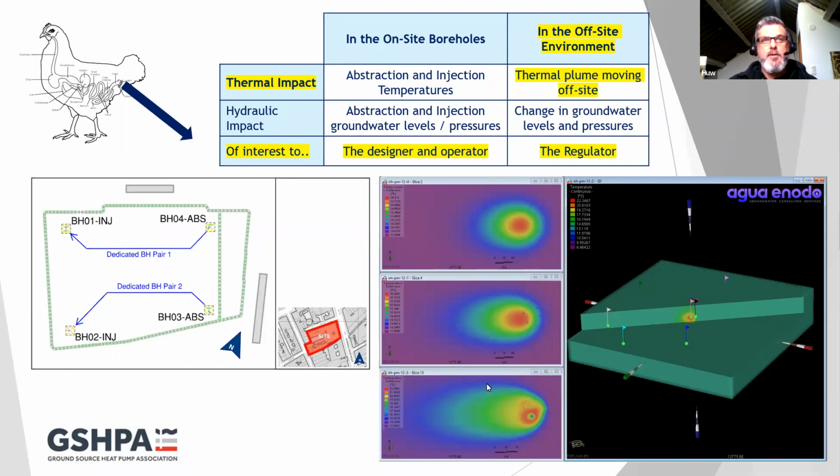And by that I mean that the amount of thermal energy that we're putting into the ground via these injection boreholes has reached such a size of plume that the thermal exchange is no longer expanding. And this is 3 screenshots, not through time, but 3 slices through the model at the same time. And you can see how the thermal plume has developed with depth of the injection.